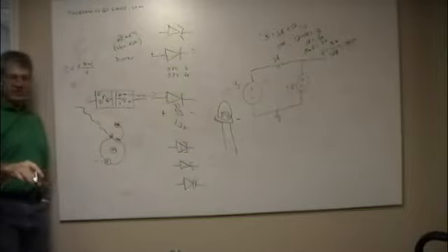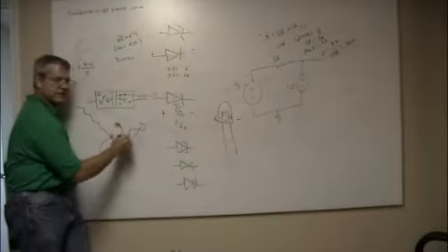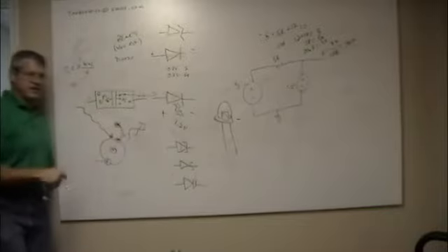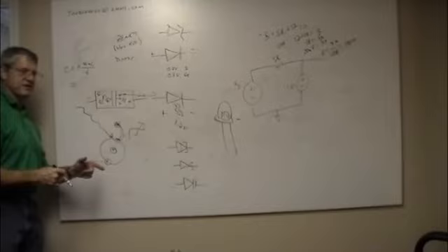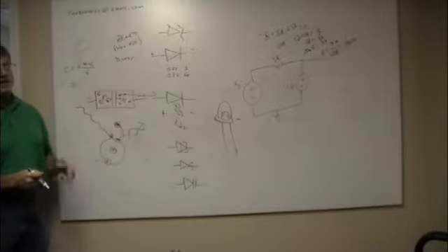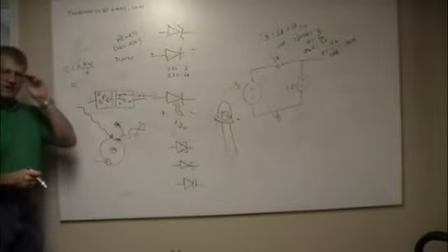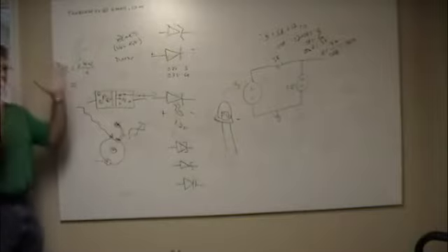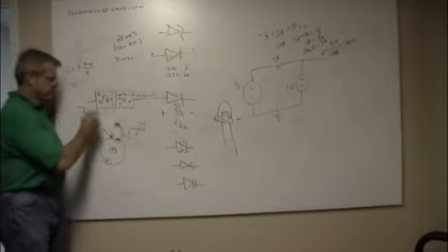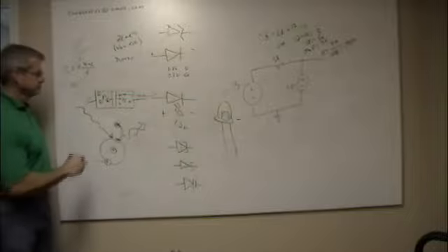And this is part of how an LED works, is when that electron falls back in, it gives off light. We make him energetic by putting electricity on him. He pops out of the valence band up into the conduction band, and then when he falls back down into the valence band on a different one, he gives off a photon. Woo! Light. The reverse happens too. Light comes in, he can pop up. If there's a voltage difference there, he can be swept away.